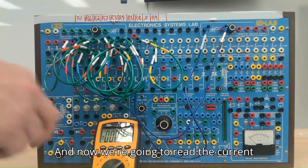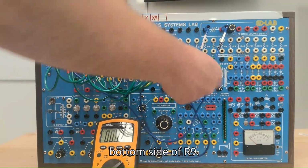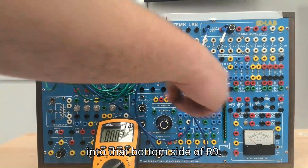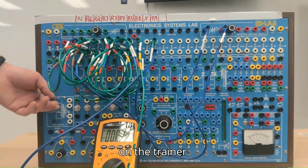And now we're going to read the current going through J12. J12 is on the bottom side of R9. We're going to put our temporary lead into that bottom side of R9 and take J12, install it into the common port of our meter. Let's go ahead, turn on the trainer.